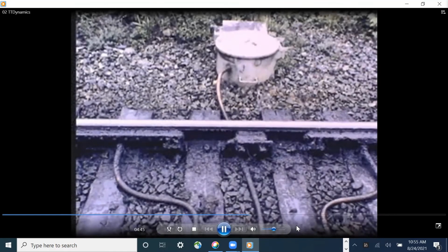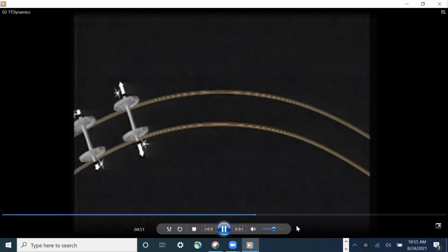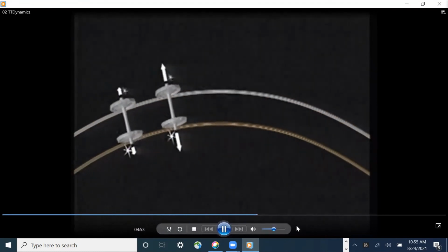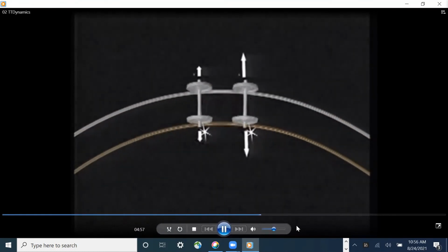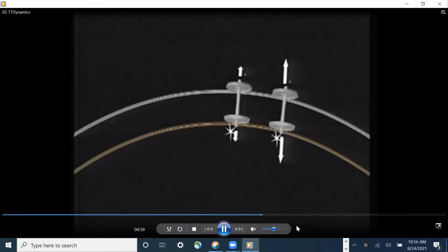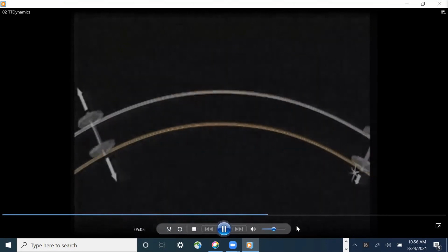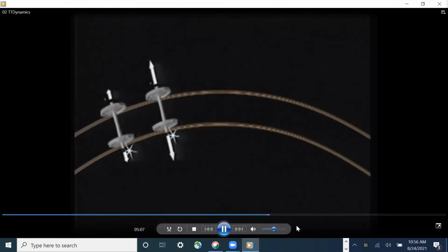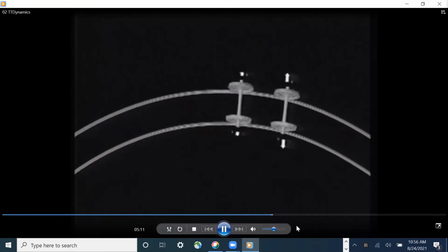Frictional curving forces can be reduced by appropriate rail lubrication. However, lubricating only the high rail increases the total gauge spreading forces, because all steering forces for the truck must be generated by frictional curving forces off the low rail. On high-degree curves, excessive frictional curving forces can be reduced by lubricating the low rail as well.